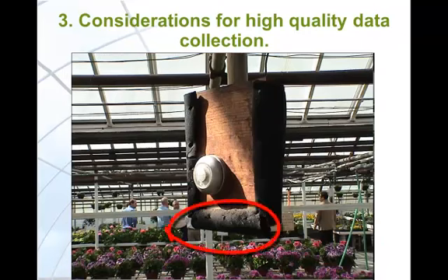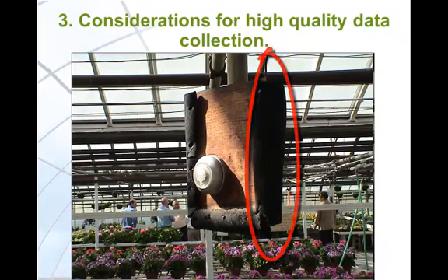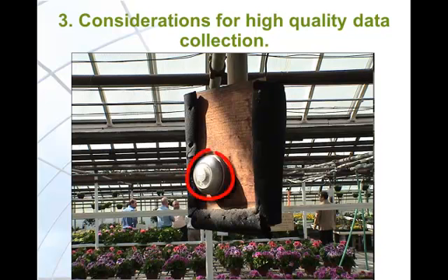This thermostat panel has been protected by foam edging so that people do not hurt themselves by running into it. This is a good safety measure. However, as you can see from the light and the shadow, this sensor is in direct sunlight. The sunlight will warm the thermostat, and the temperature reading will not represent the ambient temperature inside the greenhouse.